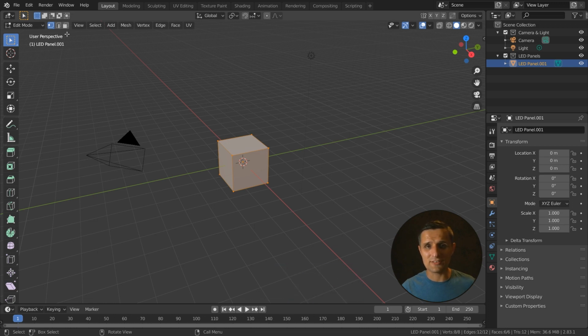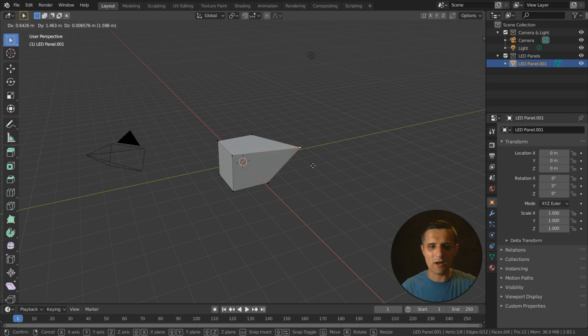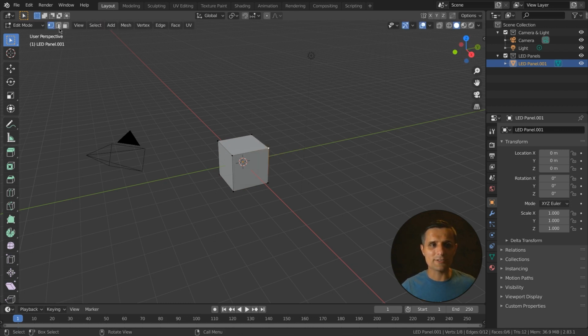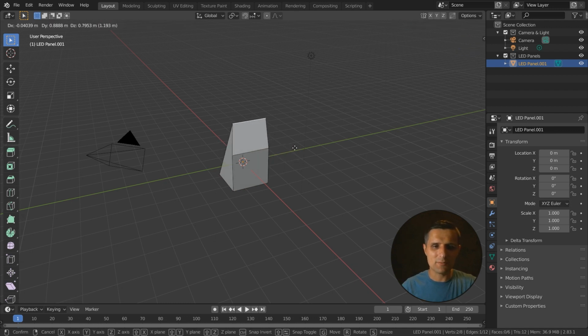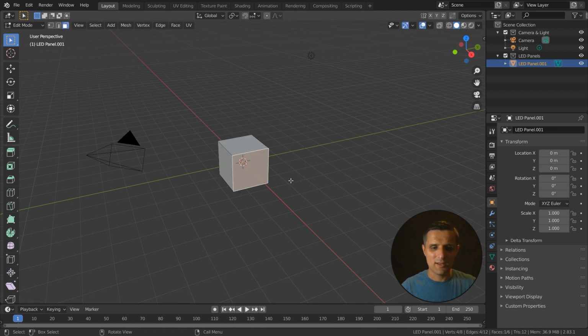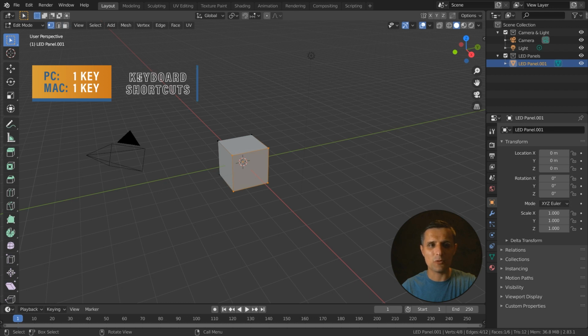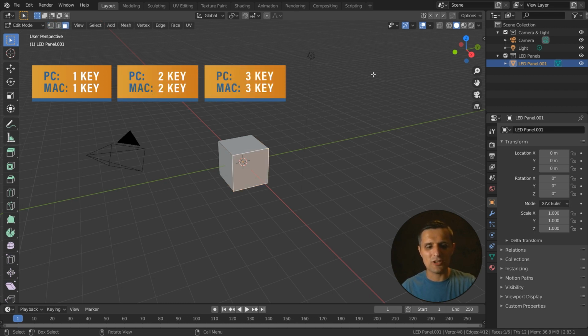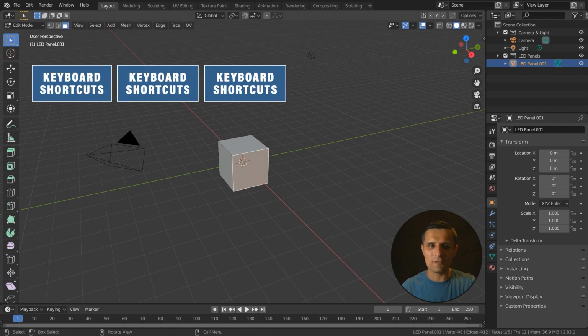Right now we are in edit mode, and you have 3 options in here. You can either work with vertices, click on vertices, select one, move them around, you can do it that way. You can also adjust edges, the same concept, move them around, and faces. Now, you don't want to be traveling all the way to this area to select faces, edges, all that stuff. You can use keyboard shortcuts. It's just by pressing 1, and as you can see, you went to vertices. 2 will get you edges, and 3 will get you faces. So you can quickly shuffle anywhere, right? You don't have to travel.